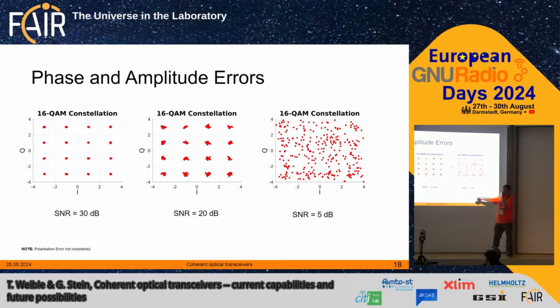To give you some examples of how the 16-QAM constellation looks with a transceiver, I made a simulation, a statistical application based on the Gaussian curve. If we have a good signal-to-noise ratio, which should be high, like the curve I showed you before, the constellation looks like this. If you put your grid, your mesh here, you can still clearly, as a photodetecting system, find out to which bits it belongs.